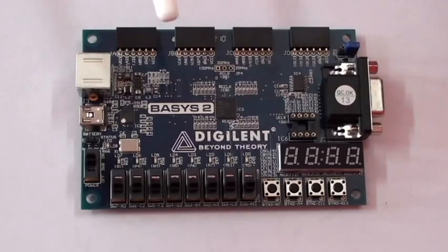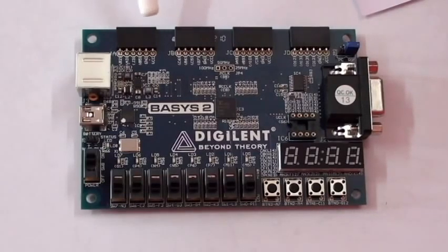It is made up of a Xilinx Spartan 3 FPGA. It has an Atmel USB controller. Basys2 is a complete board as it has ready to use hardware on it. It has a large number of onboard I/O devices. With the help of this, a number of designs can be created. There are 4 standard expansion connectors which allow designs to grow beyond the Basys2 board, where we can connect PMODs for analog and digital I/O modules like A to D and D to A conversions, motor drivers, sensor input, and many more features. A USB cable provides power as well as a programming interface.